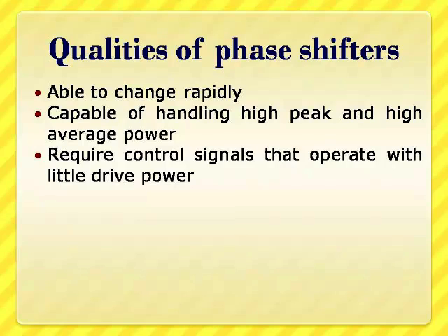What are the qualities we expect for these phase shifters? First of all, we should get a rapid change in the phase shift, and it should be able to handle high peak and average power. It should require very few control signals to operate, and hence it should be able to get the required phase shift with a very small amount of drive signal power.